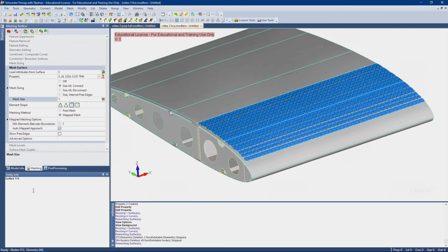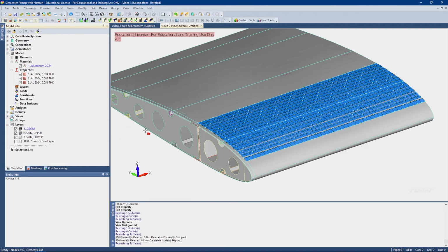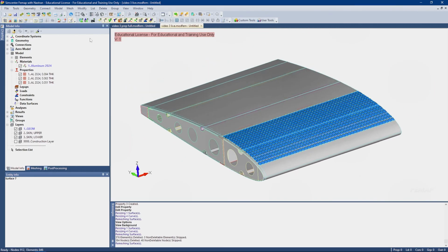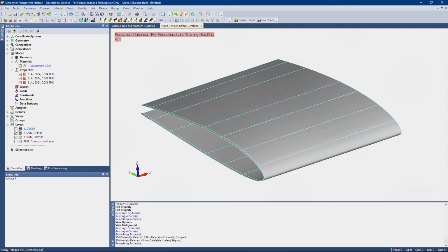So essentially we're just going to, am I in the wrong layer? I am in the wrong layer. I'm going to do this once per video, I think. So essentially, layers are buckets to put parts of your finite element model in. Whatever layer you have selected, so you can say I have geometry selected because it's a blue color, is going to be the layer that the element you create is placed in.